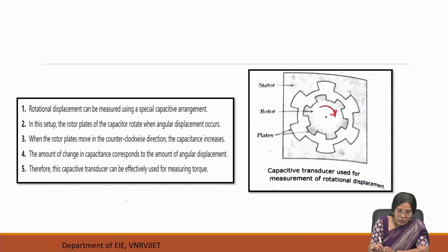When this rotor rotates in the counterclockwise direction, the capacitance is increasing. So like this we can measure the angular displacement.